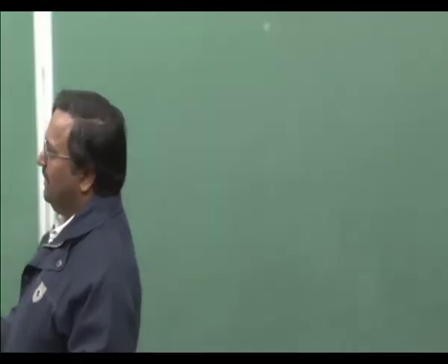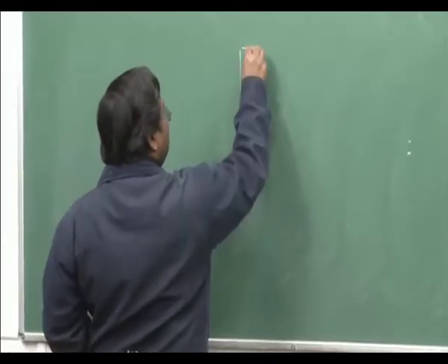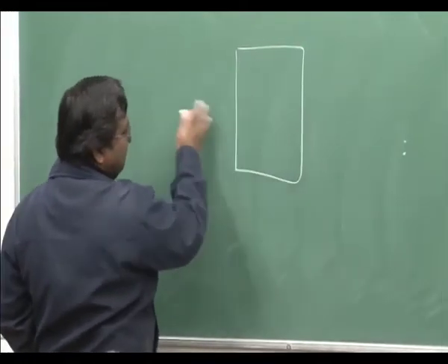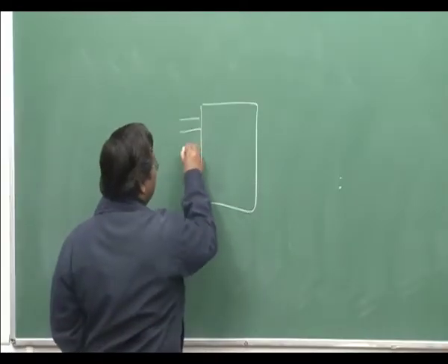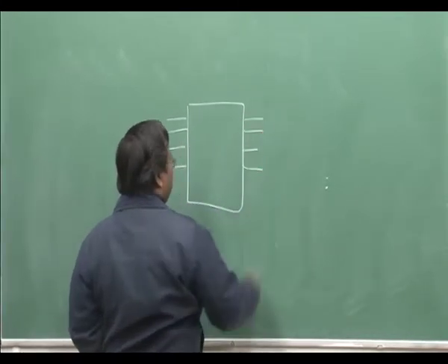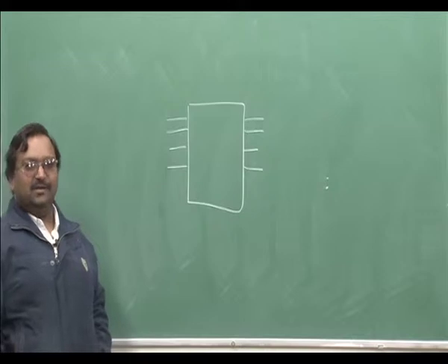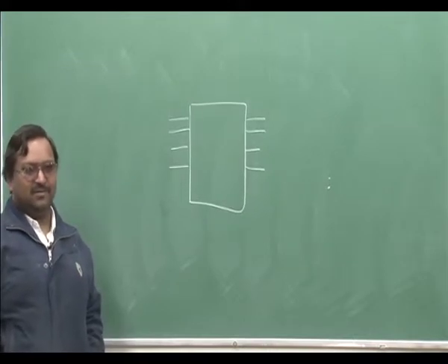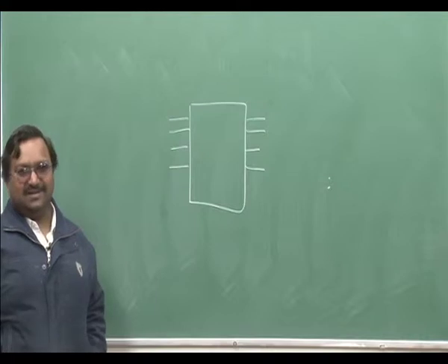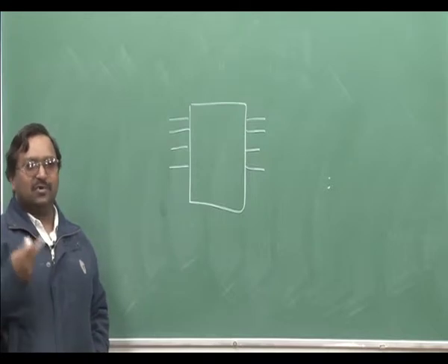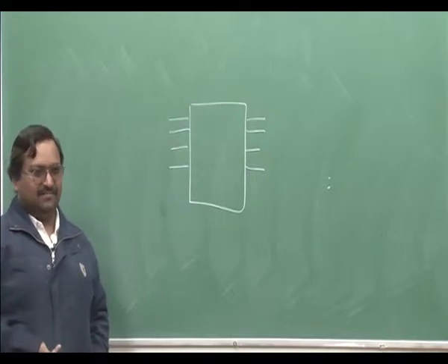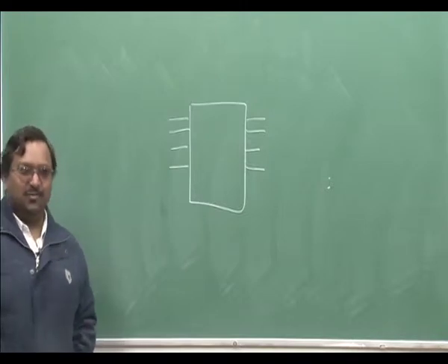Now the question is this. Some people can say, okay, I have this crossbar, and I am showing the crossbar outputs on this side and this side, not at the bottom. So where should I put the buffer? There are 4 lines, for example this 4 by 4. I cannot insert a buffer inside a crossbar as of now. A crossbar is a cross point. In every slot I just snap certain cross points, and this set of snapped cross points keeps on changing in every time slot. So where to put the buffer? Can I put it at the output?